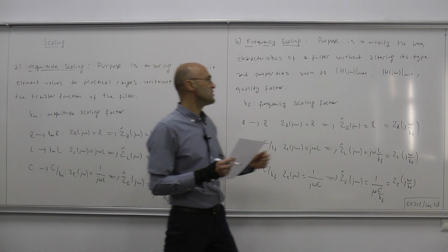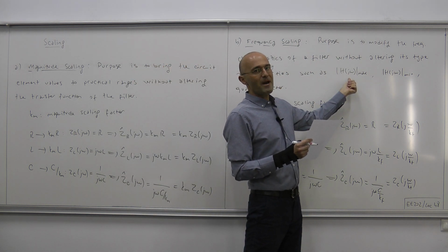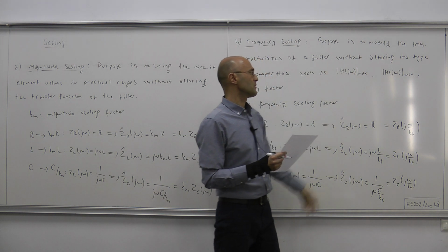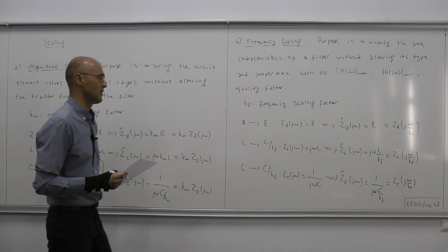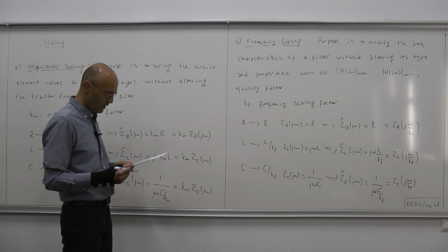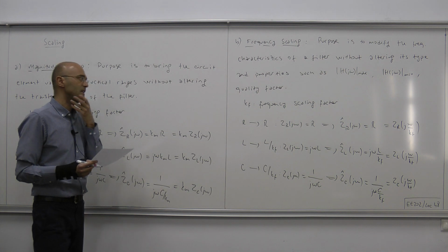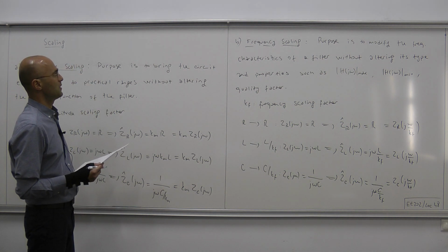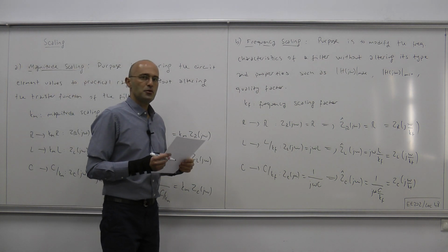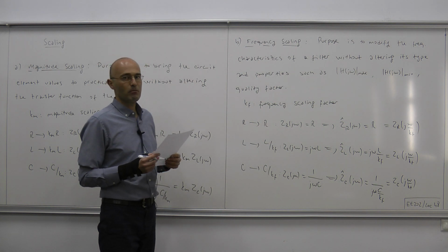But what changes is the frequency at which the maximum is attained, for instance, the center frequency for a bandpass filter. Now, this is magnitude scaling, this is frequency scaling, and let's apply this pair of procedures to an example filter design.